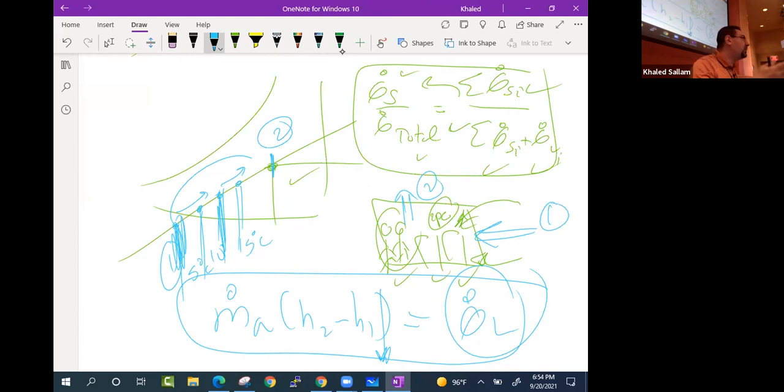Problem with the COP, problem with insulating the ducts. But at the same time, saying, okay, then let's just cool 5 degrees so that our cooling coil will have a very good COP. The mechanical vapor compression will have a great time, just cooling 5 degrees, it's a piece of cake, right? The problem is m dot air will be so big, right?